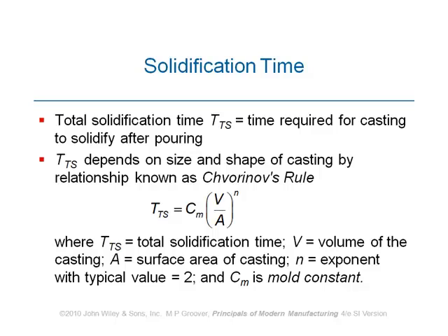What we have got in this equation, as I said, V is the volume of the part or cavity, A is area, N is an exponent which is often 2, depending on some characteristics of the casting process. In our problems we always substitute 2 for N. So it's simple.